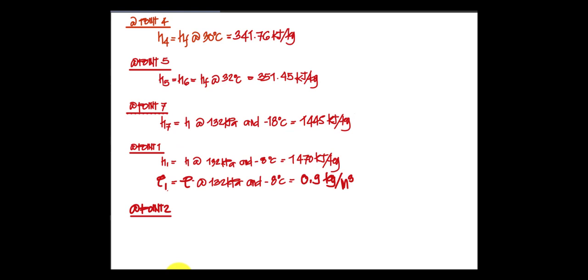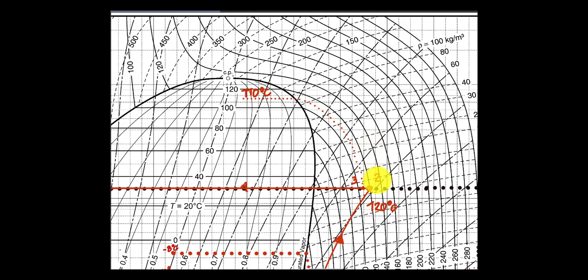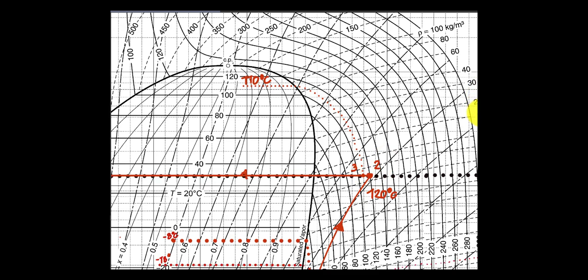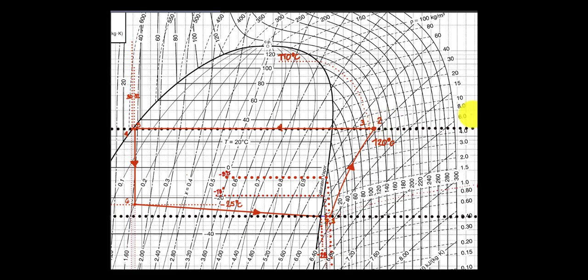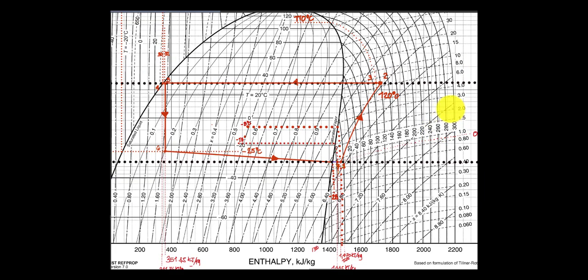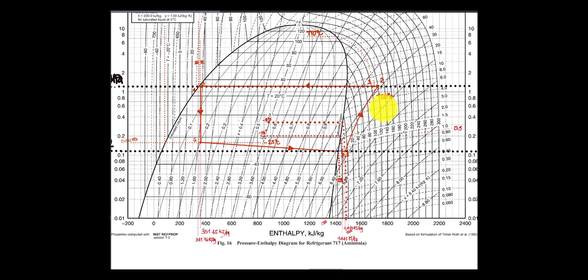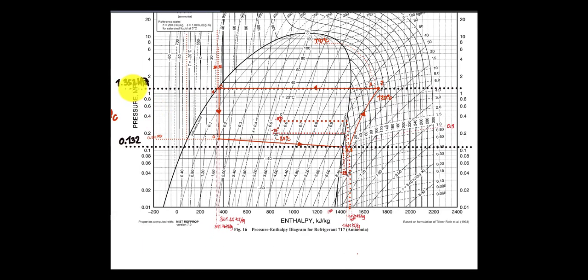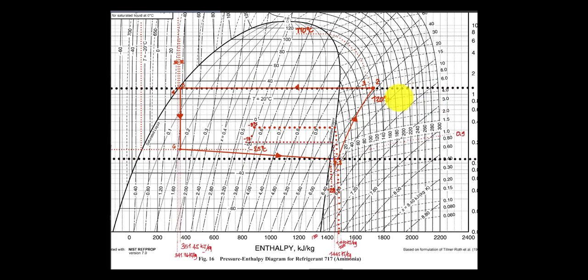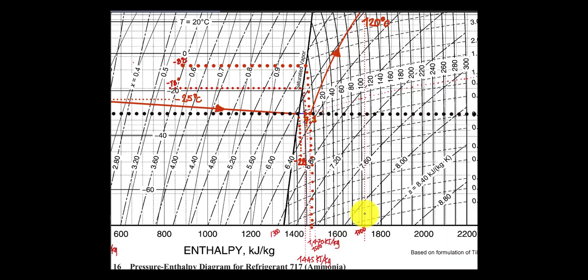Now for the enthalpy at point 2, that will be the enthalpy at 1352 kPa and the intersection with 120 degrees. Looking back at the pH diagram, 120, okay, this one, so we can draw the line here to determine the enthalpy at this point. So what is the enthalpy of the intersection of 120 with the corresponding pressure of 1.352 megapascal? This is in our pH diagram.